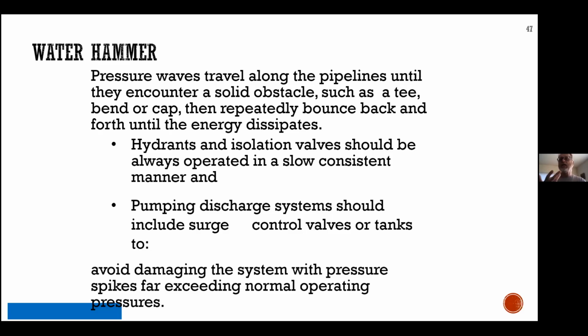And the temptation, especially if you're dealing in the middle of the night with a bad water main break and the resident's saying, my basement's flooded, shut it down quickly. And it's very hard to tell them, oh, we're shutting it down as quickly as we can. And the rule of thumb, basically, an old superintendent told me, was a minute per inch of diameter. So an 8-inch main, 8 minutes to shut it down? No. If the valve is operating, I've seen operators shut it down in 30 seconds.